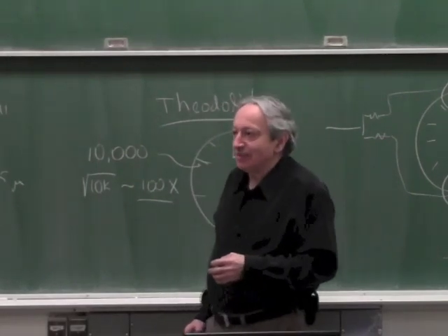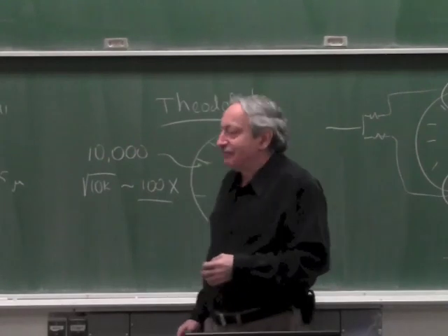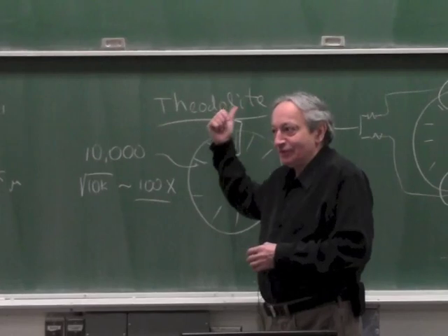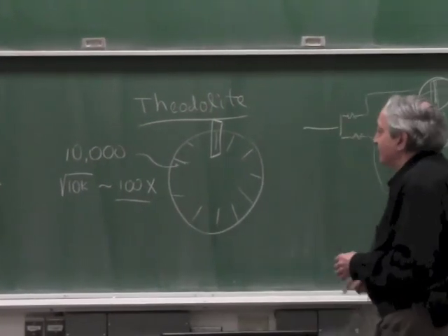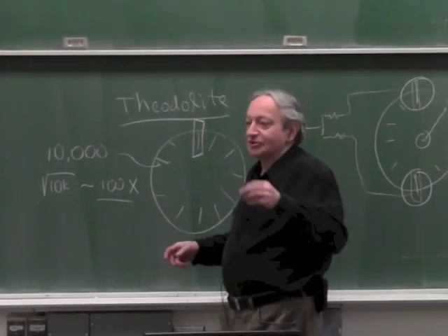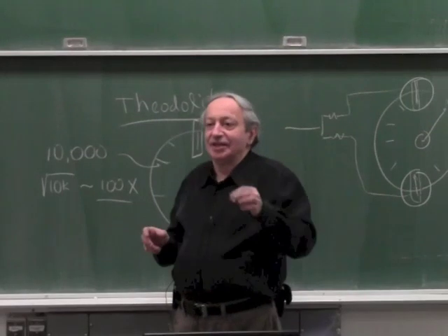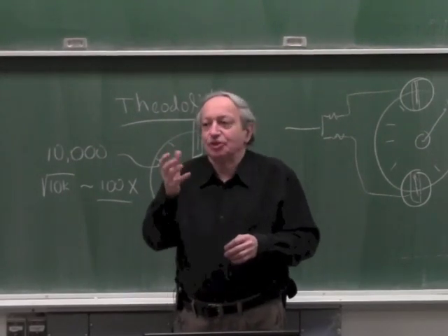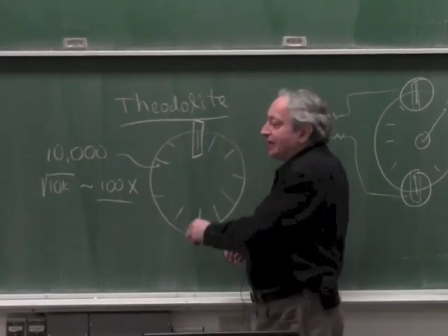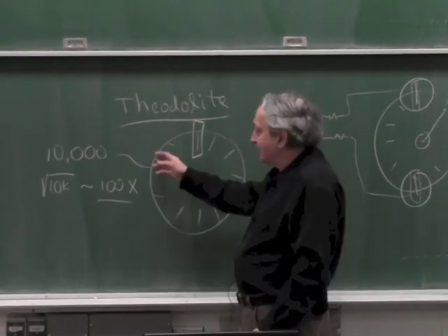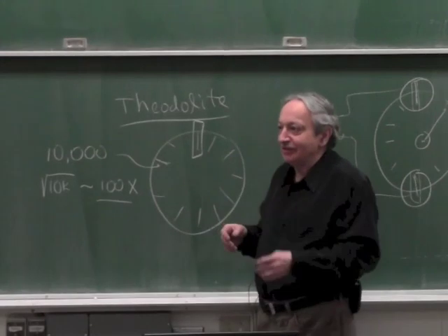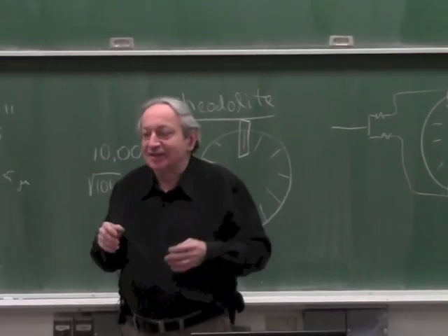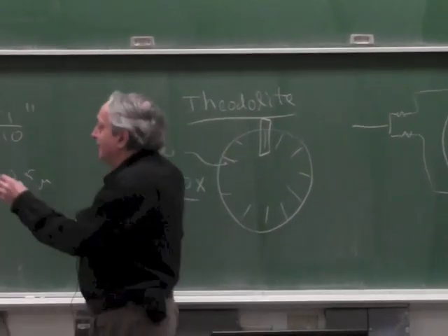And I gave the example how Ramsden did the first sextant, which is also across the wall here, and it's worth your while to have a look at what it looks like. So the way he did it, he took microscopes and aligned them in such a way that each position of the wheel, the microscope had to stay aligned, and then he corrected the teeth of the gear by filing or by lapping until the microscopes always lined up with the lines.